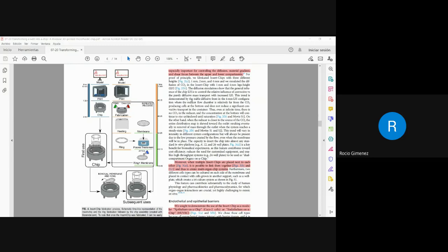The use of 3D printing enables the design of the platform to be quickly modified, and it reduces the need for multi-step fabrication. The insert chip is made of 3 parts: the base, the membrane, and a sealing ring. The base is fully made with a 3D printer. The membrane is interfaced into the insert chip with a ring made of PDMS. And to ensure complete adherence between the membrane and the sealing ring, they use plasma and APTES.